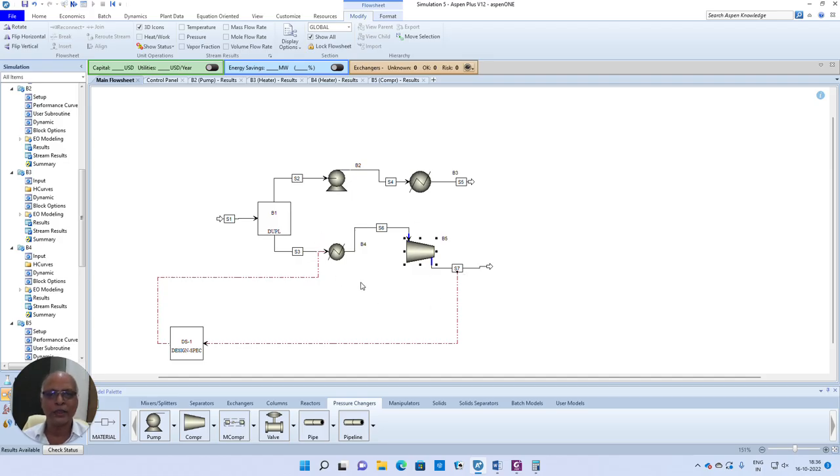You know, the total energy is not a path function, it is a point function. Because the initial and final states by both these paths are similar, the total energy required is going to be similar. So you will not be able to identify from the first law of thermodynamics or from the energy requirement which of these options is going to be better.